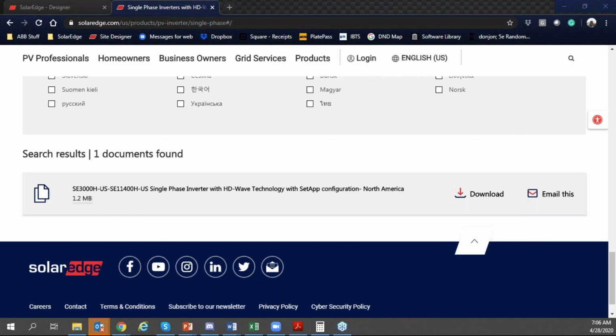I grew up in Arizona and did a lot of installation in Arizona. Every time my snowbirds left for the summer, I was getting tons and tons of phone calls about their systems being offline and not communicating. So I'd roll a truck and the system's working great. They just turn off their internet when they leave and they forget. With cellular, I didn't have to worry about that. I always had communications with the system. That way I knew, oh, this Mr. Jones's inverter did go down, and I could address that.